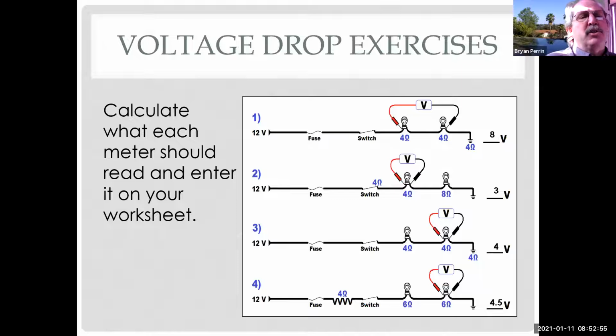And especially when we look at circuits with problems and how we can see this where we might have a problem. What I'll tell you is most of the electrical problems on the vehicle are either caused by a failed component or excessive electrical resistance in the circuit. So we rarely have a short. We don't have that many opens. We have a lot of excessive resistance, a lot of bad connections. So on the car, this is the most common thing that we're actually diagnosing in the electrical.